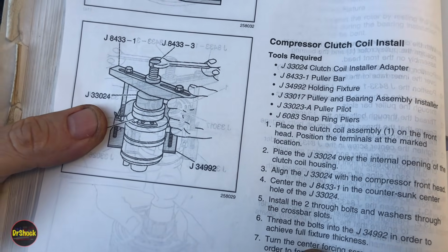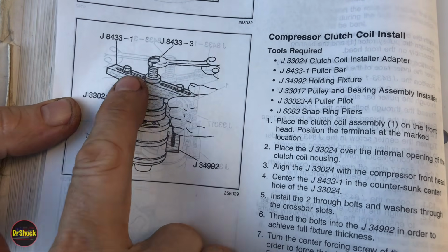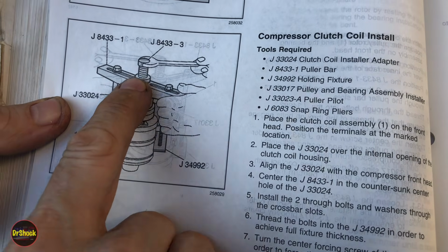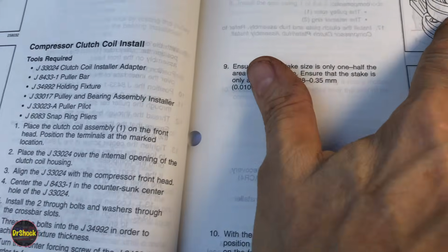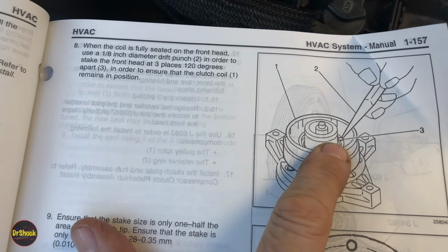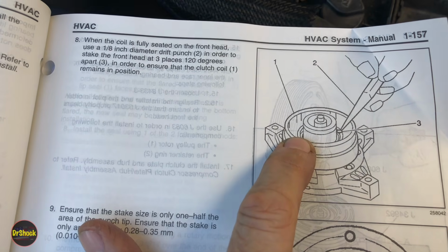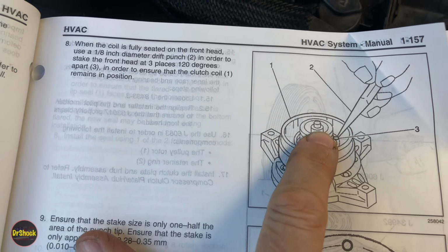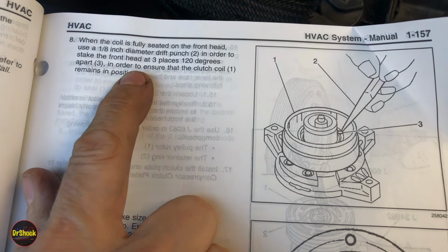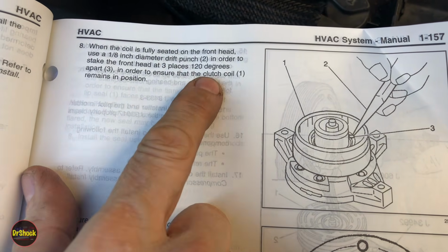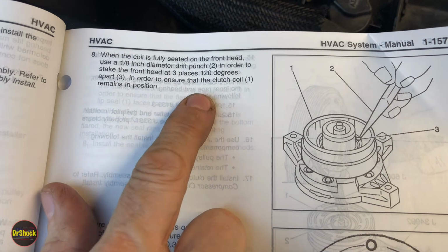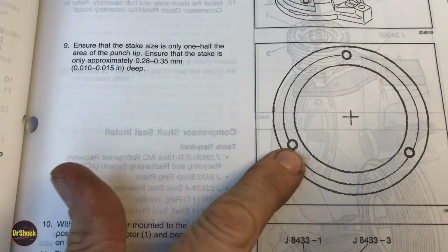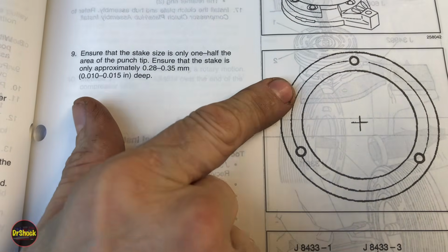So they talk to you about putting the coil on with a similar kind of tool that looks like a puller, but it's a press and a different type of pilot, right? And then they talk to you about staking the aluminum to the outside metal in 3 places. Remember I said I was expecting to see that. Looks like GM doesn't do that anymore. But what they used to do is stake it at 3 places 120 degrees apart to help keep it from coming out. And this just shows you like that. They just stake it in these 3 spots here. That's how they would have put that on.